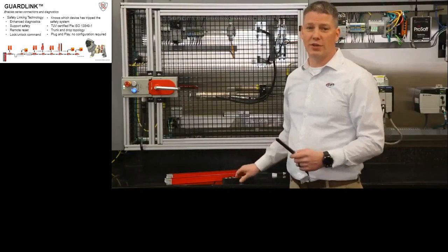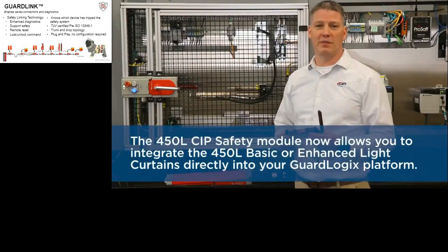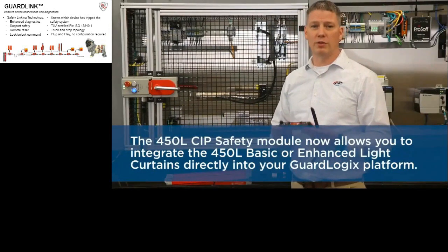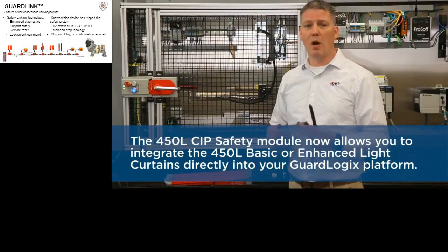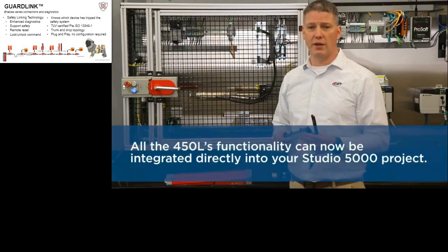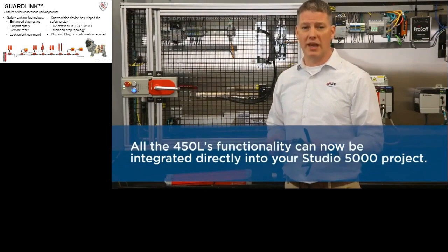Released just this year, the 450 SIP safety module now allows you to integrate the 450L basic or enhanced light curtains directly into your GuardLogix platform. All the 450L's functionality, like muting, blanking, and cascading, can now be integrated directly into your Studio 5000 project.